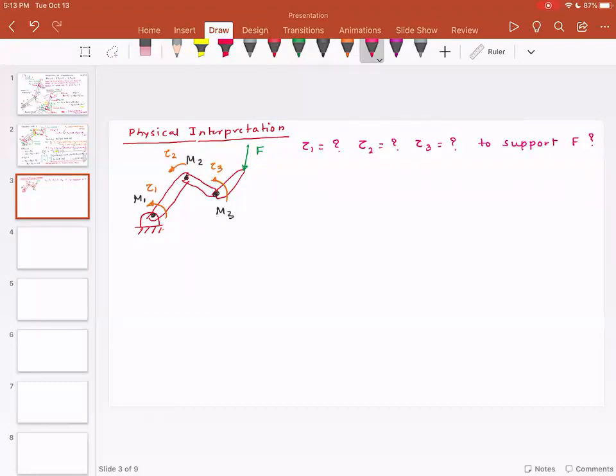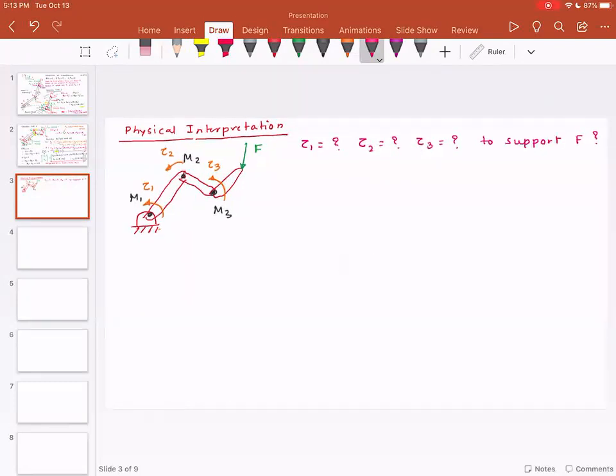There is a slight difference between application of torque and holding torque, and I will get to it in just a second. So the idea is, if I give you the value of F based on the Jacobian, you should be able to tell me the values of torques. And the equation is this. Let me derive the equation, and then I'll tell you how it is interpreted. So all this comes from something called the method of virtual work.